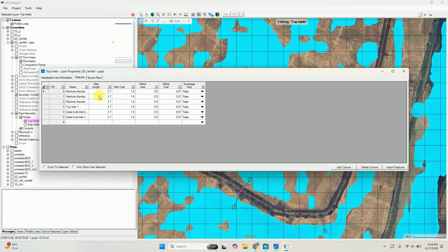So like this circular pipe you are applying in the system, so you have to give a circular manhole there. And what will be the length of that manhole? Like 2 pi r, yeah, pi d. So this is pi d, nothing much, pi into d, the diameter of your conduit, and this is the weir length.